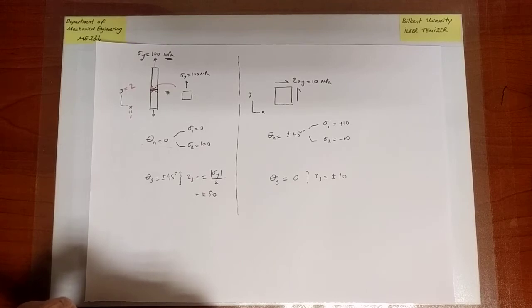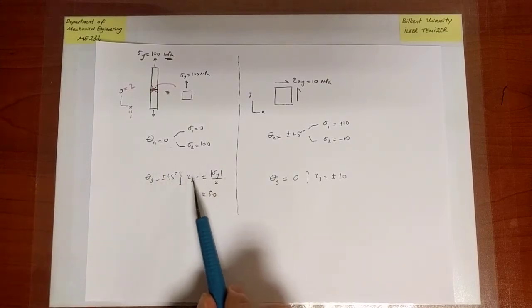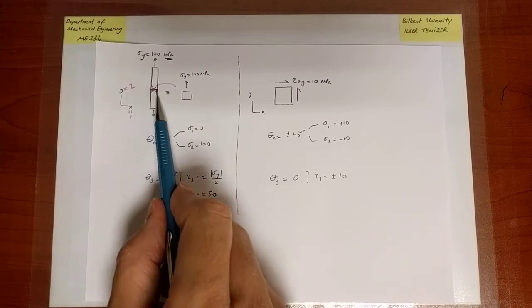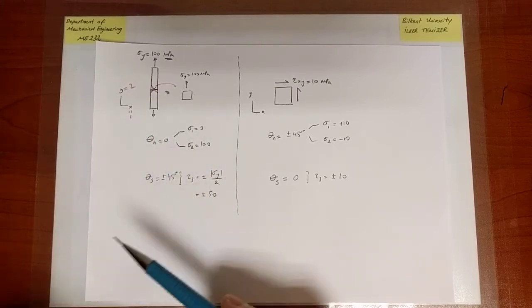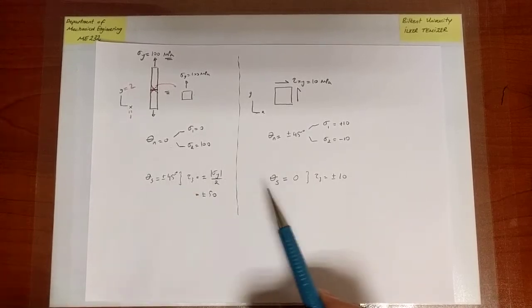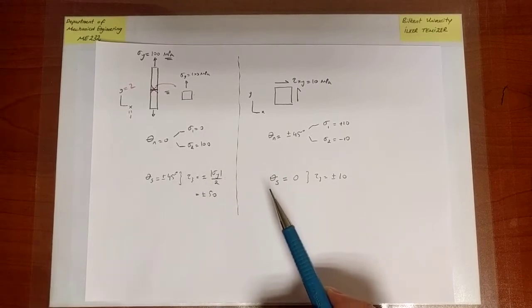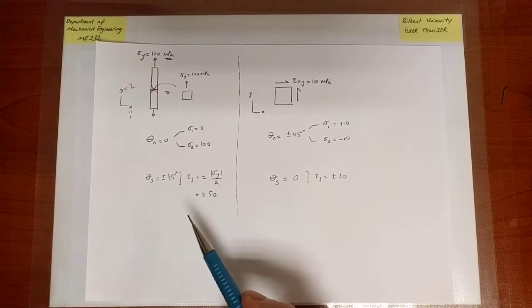And that is because metals are sensitive to maximum shear, okay? Not in absolute terms, we will state rigorously what the criteria are, but we see now that the maximum shear occurs on planes that are oriented at certain angles close to, well, in this idealization, plus minus 45 with respect to the axis of loading. So now you see, we are able to deduce with the tools that we have the planes on which maximum normal or maximum shear stress occurs. And ultimately, that's going to help us with the decision of whether failure is about to happen or not.